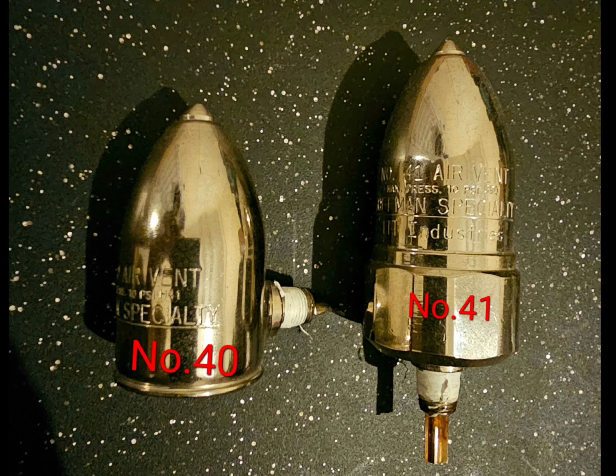That's exactly why cast iron radiators hold their heat that much longer. They're made out of thicker metal, so it naturally holds more heat. Steel convectors aren't designed for that. They got these fins, and steam and water does not actually enter the fins. It just passes through the tubes, and the fins pretty much are just a means of dissipating heat. But cast iron radiators will hold the heat better.